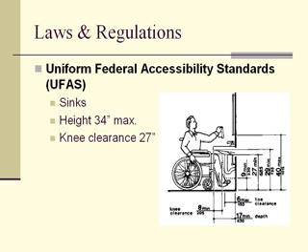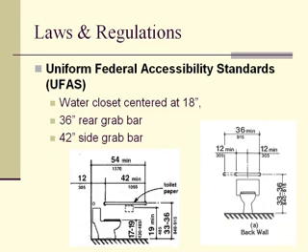If a mirror is too high, a full-length mirror can be installed within the restroom to meet the standard, if it would imply too much work to tear up existing elements. Also, cabinets within these, like medicine cabinets, should be no more than 44 inches above the floor to the top of the bottom cabinet. So that's also a requirement if some of these mirrors have built-in cabinets in them.